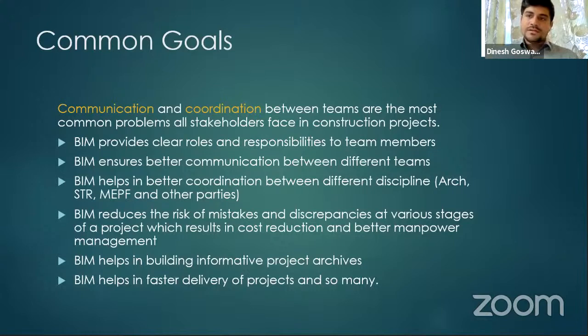Once things are decided, everybody knows who will be responsible for what. This results in better communication. If I know that these people will be responsible for MEP services, I can contact them and coordinate with them easily. This eliminates the communication problem. After we have decided these responsibilities and deliverables, we document everything in a document called the BEP, BIM Execution Plan. We circulate this BEP document to all the teams so they can start their work.